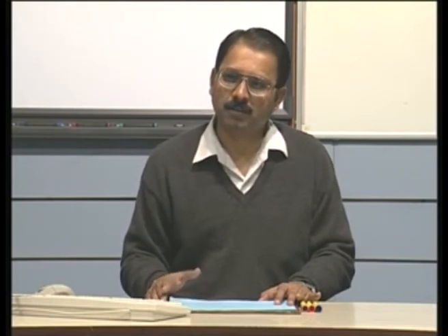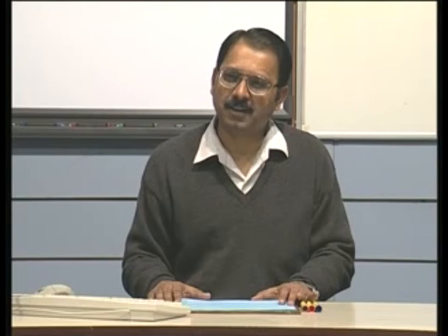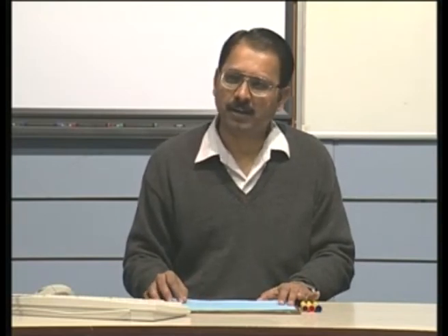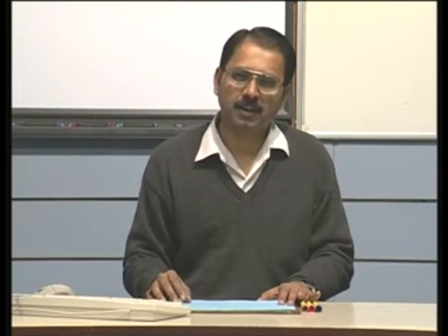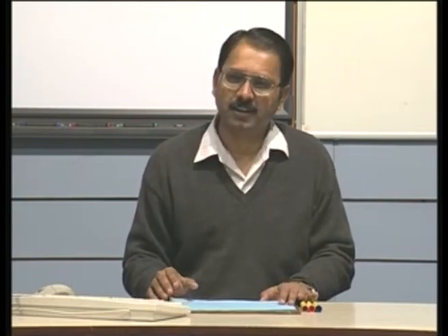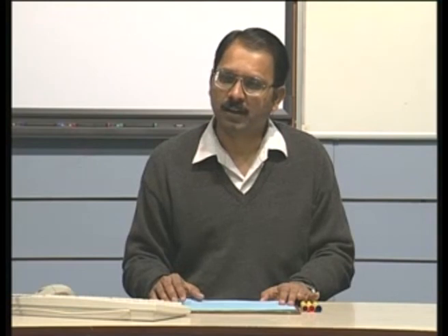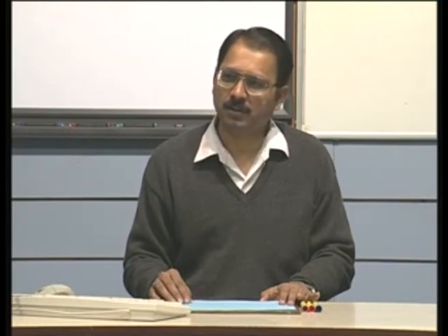That is another very important curve. In fact, one of the interesting aspects of Bezier curve is it is not a very old curve. It was defined in the 1960s, that is the first time a definition of the Bezier curve was given by a person by the name Bezier himself, who was an automobile engineer, particularly to arrive at certain forms for automobile applications. And as I said, it is an approximation curve, and the most common form of Bezier curve is a cubic Bezier curve, which is defined by again giving you 4 points as an input.